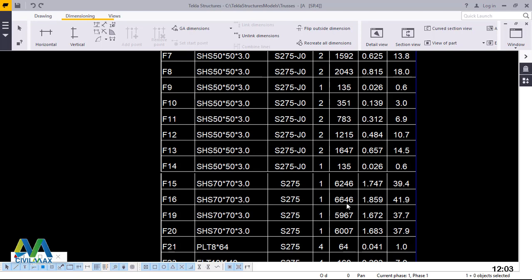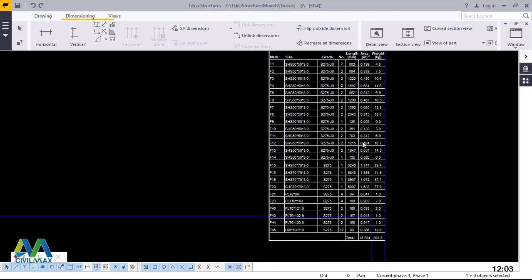So if you want to do the procurement of the materials, we'll take this length, then add to the opposite length, then how many trusses do we have? We have 30 trusses. Now this length will multiply by 30. Once we multiply this by 30, divide with the standard length of the steel for the square hollow section, which is 12 meters. Divide that result by 12 meters, you'll get a total number of the top chord to be bought. Now let's zoom out and go to the next part.